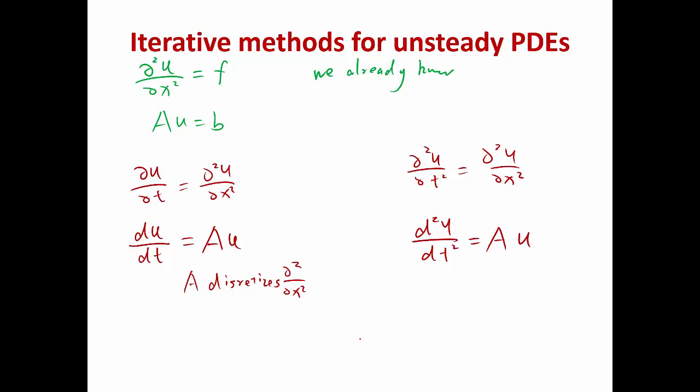How small your grid has to be near the wall determines how ill-conditioned your matrix is. And usually, if you have a very thin boundary layer, it's a lot better to solve the whole matrix using implicit methods. So if we use, let's say, the simplest implicit method, backward Euler, to solve this, we are going to use u of time step n plus 1 minus u n, divided by delta t, equal to A times u of what? n plus 1.